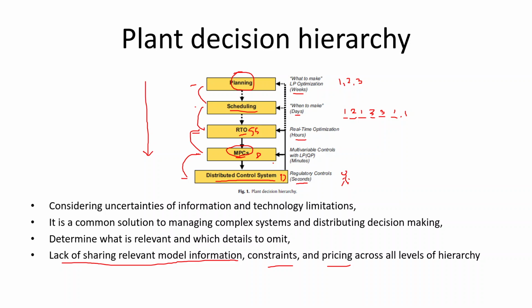In one example, for things that they cannot model precisely, they will use something simple, like a linear system connecting the x and the y, the input and the output, and then use that as part of the dynamic process model. Then we use that in what we call MPC, or model predictive control systems.